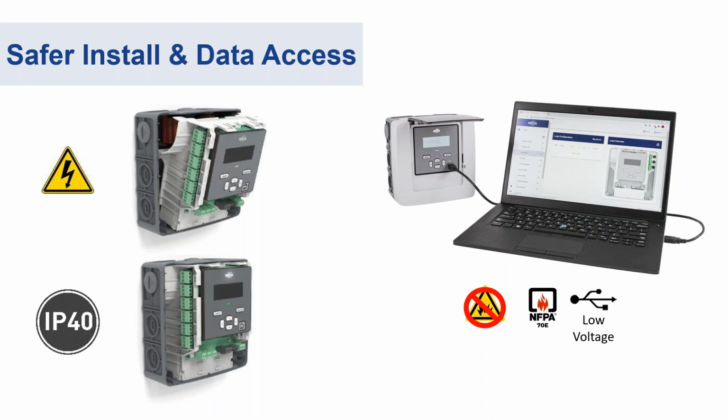When you're talking about Rogowski style CTs, there's much more headroom on the amperage rating for those. The 12, 24, and 36-inch Rogowskis that Setra sells can handle up to 5,000 amps of draw. And so I think the range is 50 amps to 5,000 amps. That's the range for the compatibility with Setra's product family.